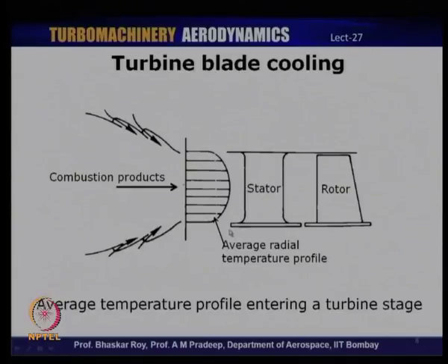It may have substantial variation in the temperature, though the combustion chamber designers would like to keep this profile as uniform as possible, but under extreme operating conditions, one may have significant variations in the temperature profile from what is shown here. And as the flow passes from the inlet of the stator to the exit, it again undergoes a change in its profile. The temperature profile entering the rotor can also be quite different,